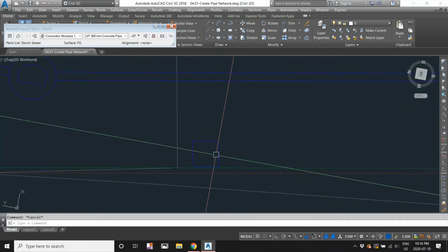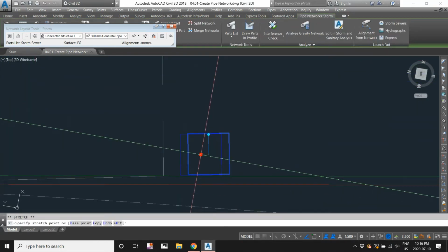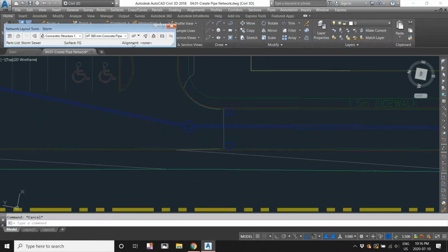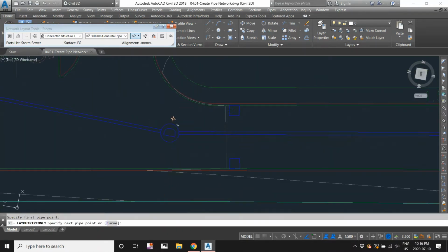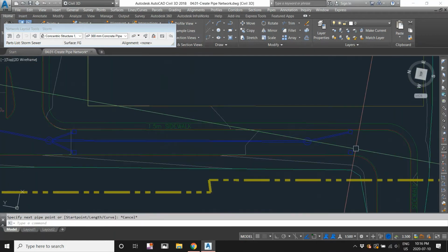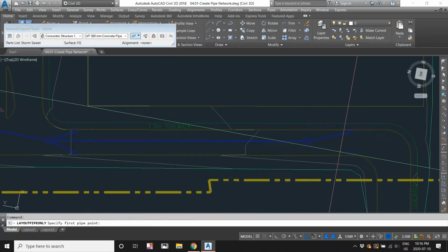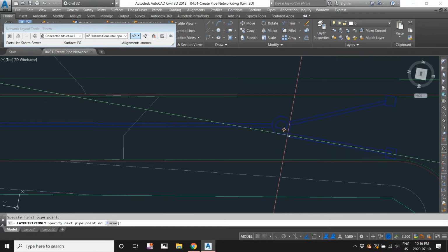And that's okay. You can move it a little bit west if you want. So I'm going to add 2 pipes now. Notice I'm hovering and I click. So I'm going to click add another pipe, add from upstream to downstream. Hit escape. I'm going to add another pipe from upstream to downstream.